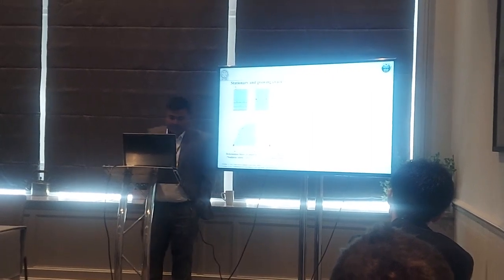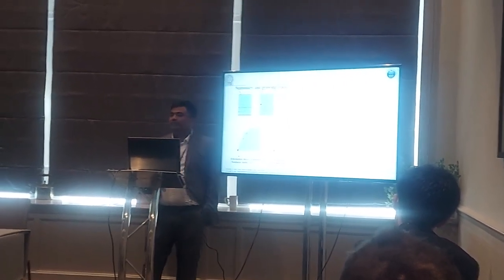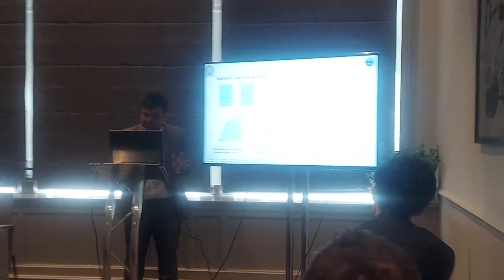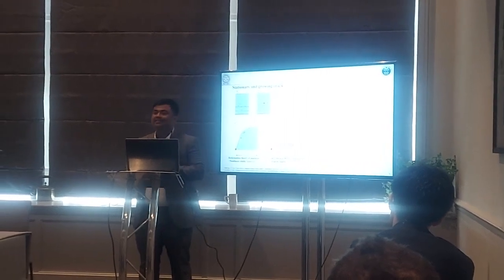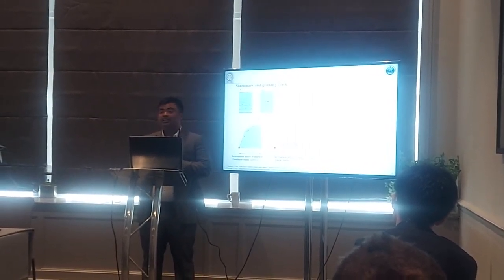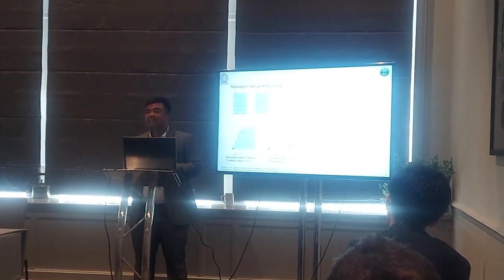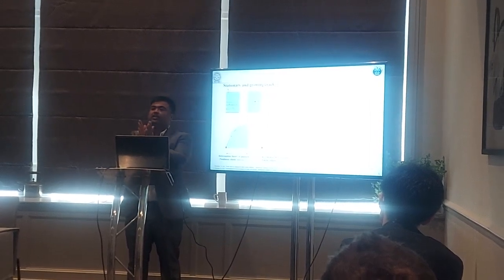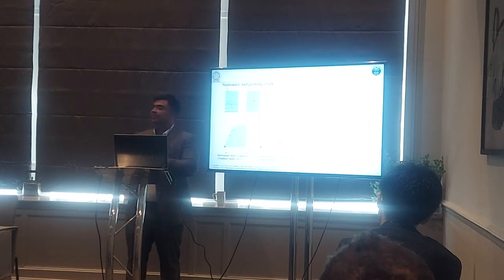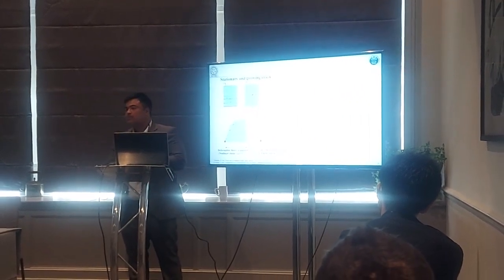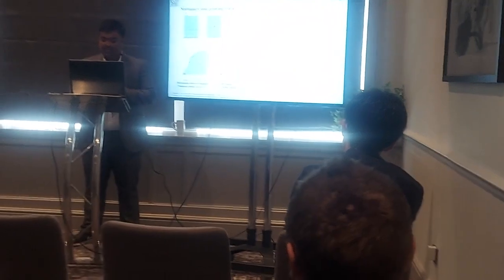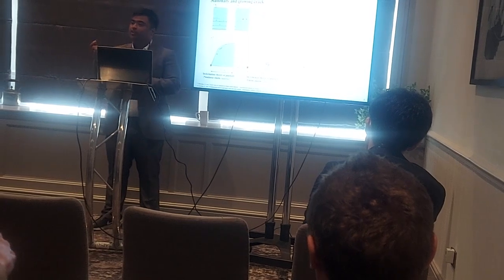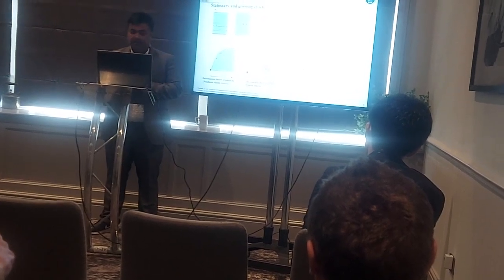And the real problem is this. Suppose the crack is growing like this, then the consideration taken by Rice fails. Basically, there is unloading. When the crack is continuously growing, just behind the crack tip there is unloading. So the concept of J Rice is like this: when you apply the load, it follows the same path. Loading and unloading are on the same path.